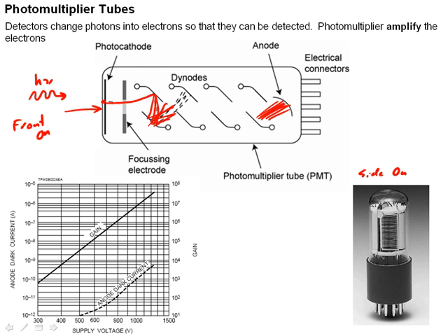If we look at the gain, the amount of gain we get from one electron being multiplied into many electrons, you can see at a voltage of 300 volts over here, you get a gain, typically it looks like on the order of about 400. So one electron is going to be multiplied into about 400 electrons if you put 300 volts across it. At 600 volts, this gain becomes 100,000. At 900 volts, we're talking about something on the order of 3 million gain.